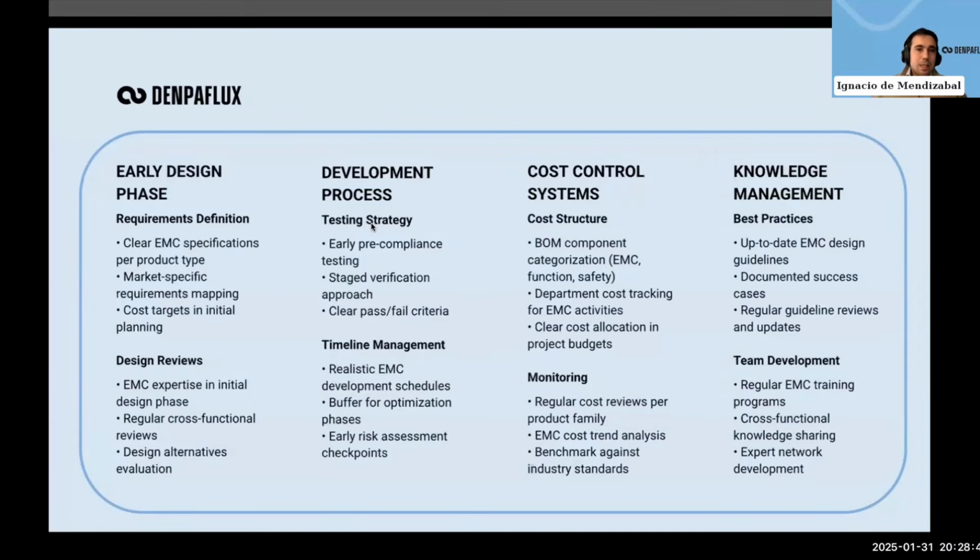A second approach is to perform some pre-compliance testing. That means that you don't need an official laboratory, you don't need to go to a notified body that is going to give you an official report, but they will measure some critical parts of the system at risk. The sooner you do it, the better insights you will have of the potential problems of your system. So you don't need to spend the whole compliance budget on that phase, and at the same time you will get very accurate results.